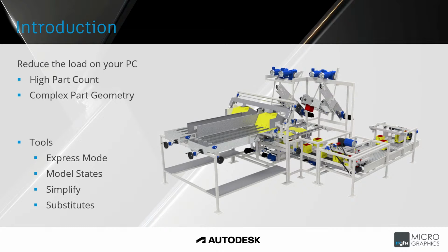But you may have multiple production lines with multiple sub-assemblies or machines within that production line, and your part count can quickly climb. So we'll look at the different tools in which we can both protect intellectual property, but also reduce the complexity of the designs. And those tools that we're going to be looking at are the express mode options when opening up large assemblies. We'll look at model states, both at part level and assembly level. And we are also going to look at the simplify option to be able to simplify down either parts or assemblies, as well as creating substitutes, where we can substitute out a single part file to represent an entire assembly.